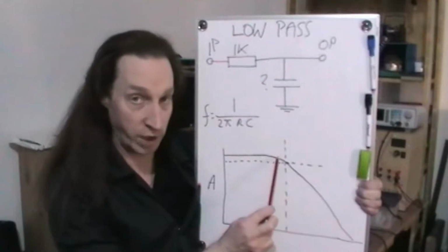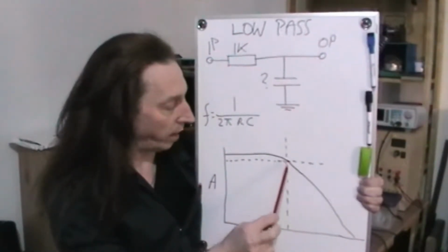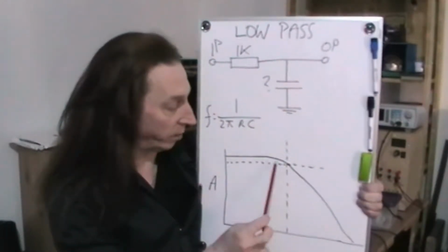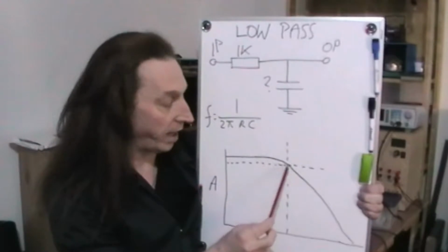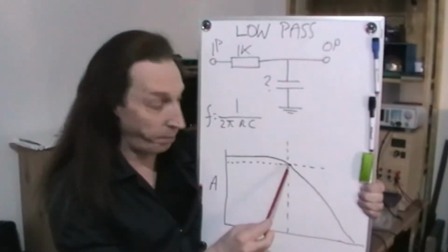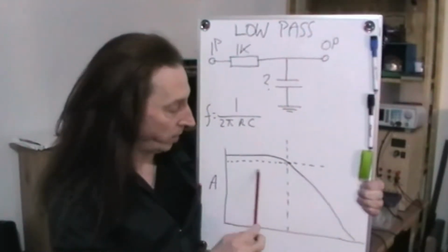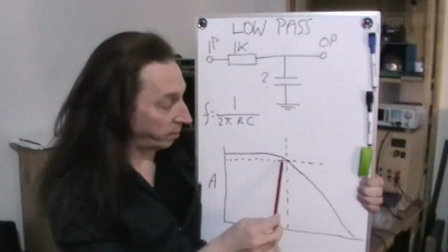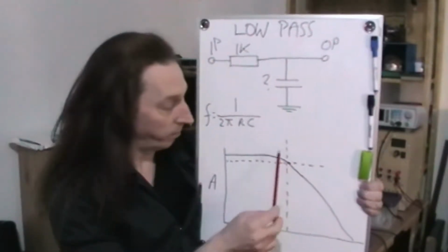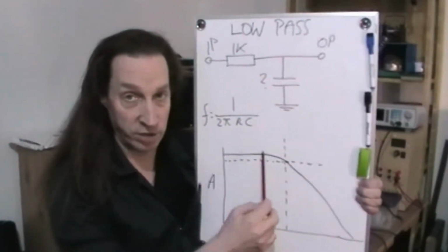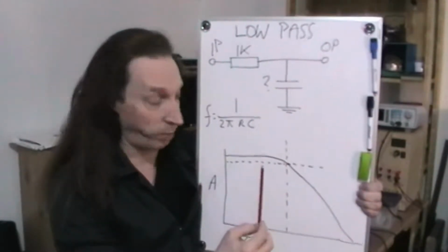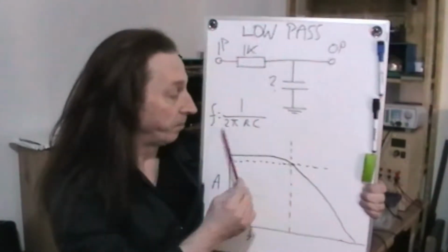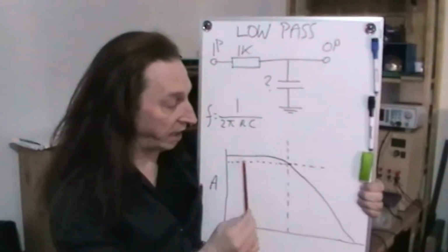And as I increase the frequency, it gets to the point where it reaches the supposed cutoff frequency where it's going to start to really attenuate it. But actually you've got this small area here that attenuates before you reach this point here, which is the cutoff. And from what I've read, that is supposedly about -3 dB. There are calculations and an equation you can use to work this out properly, but I'm not looking at that this time. What I'm just looking at is this capacitor and frequency against how much it'll attenuate.